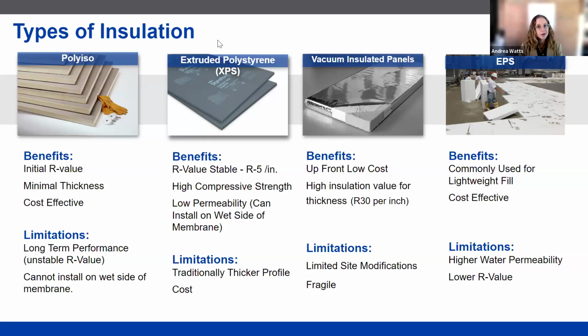This material is very lightweight. It can be very cost effective. However, it will absorb more water than an XPS, making it less of an ideal installation for the wet side of your roof membrane. Still can be used, though not as recommended as the XPS. So if we go to the next slide.